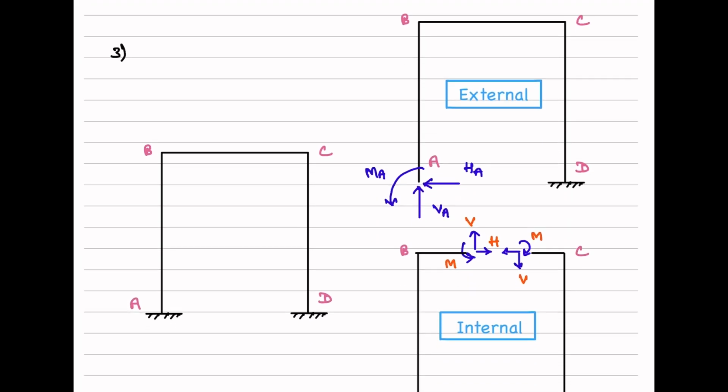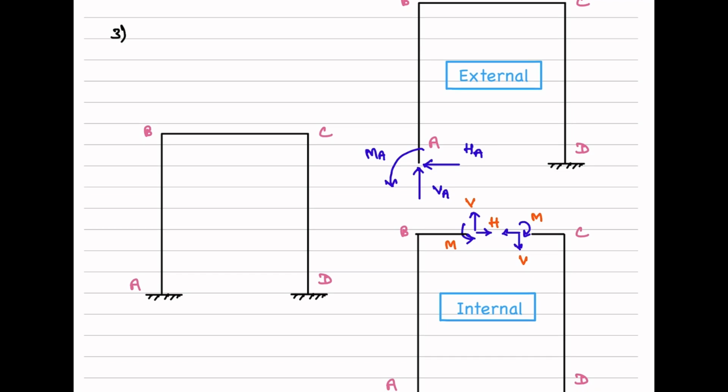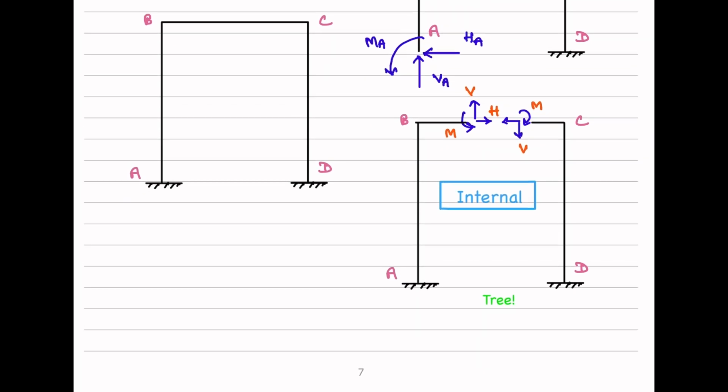In this one, we'll establish that whether we call the static indeterminacy internal or external is one's own choice. Why do I say so? Because in this problem, if we approach this problem by the way how we usually solve, SC is given by R minus 3. Here we have 6 reactive components, so 6 minus 3 equal to 3. Right? That means there are 3 excessive reactive components which can't be determined using equations of static equilibrium. Either one can choose the tree to be here or here, and just considering that the unknowns are present here. If that is the approach, we can say that this indeterminacy is external, but that is not the only way in which this problem can be solved.